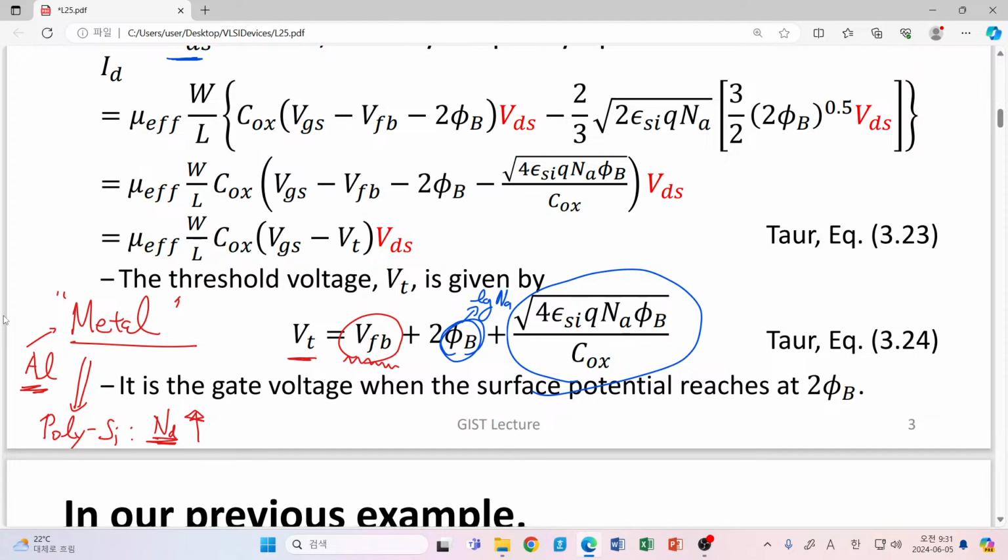So there was no chance for us to control this dopant density. So the rule was just to increase our polysilicon gate doping density as high as possible. But now we are in the third age, and now we have a metal gate once again, and fortunately now we have some capabilities to adjust the work function of our gate metal.